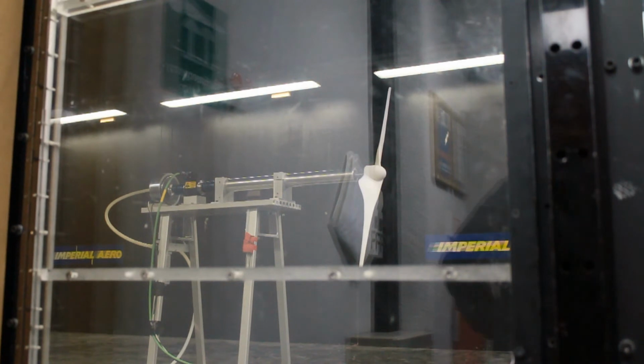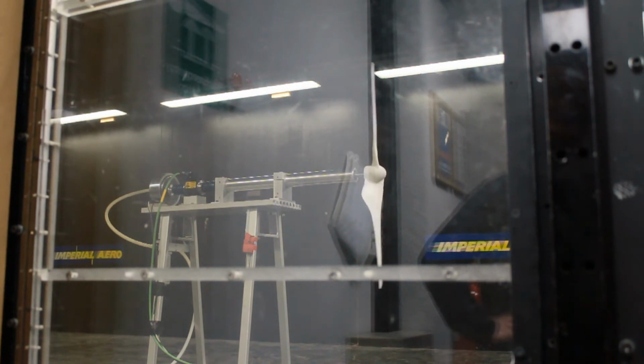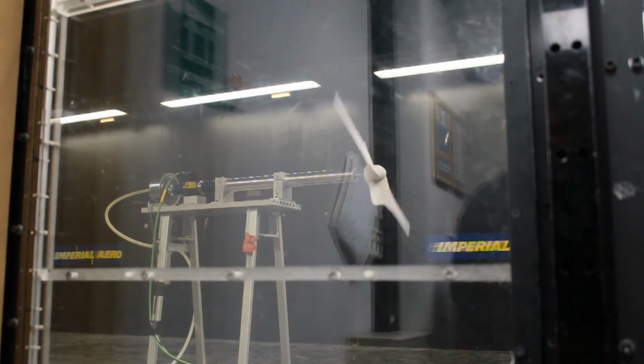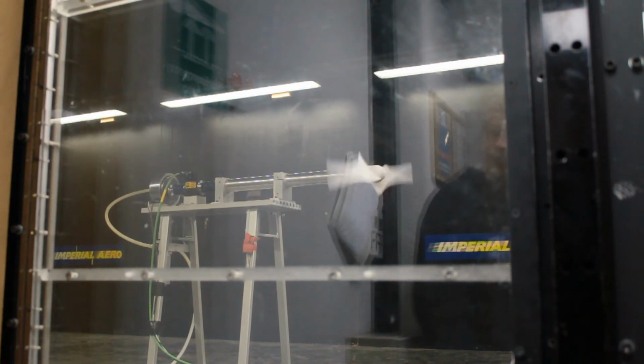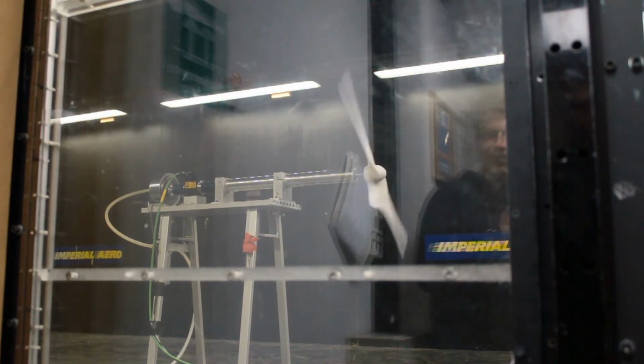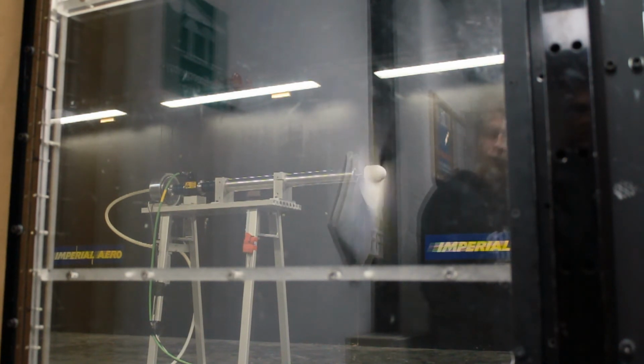We started the test by adjusting the wind tunnel to one of the required test speeds. Again, we allowed the turbine to spin freely until it had reached its maximum RPM. The hysteresis brake applied a controlled deceleration to the turbine, whilst torque and RPM were measured. When the preset minimum RPM was reached, the wind turbine was accelerated via a controlled reduction in braking resistance.